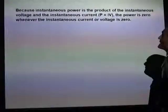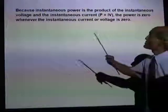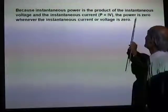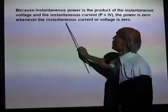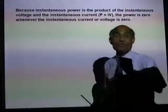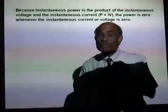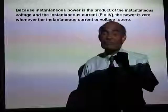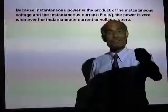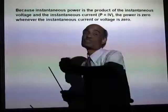Now, because instantaneous power is the product of the instantaneous voltage and the instantaneous current, the power is zero whenever the instantaneous current or the voltage is zero. Now tell me, in the case of the resistor, we said the instantaneous power is always positive, because when the current is negative, the voltage also is negative.